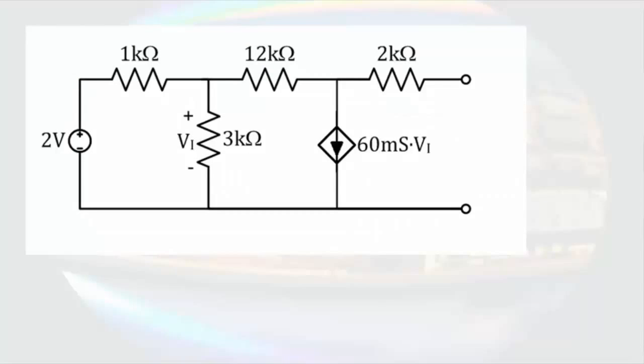If we remember way back to the beginning, the definition of resistance is a ratio of electric potential to current. So if we want to know a resistance, we can apply a test source and see what the response of the circuit is. That will generate a voltage to current ratio. For example, if I were to supply a known current to an element and measure the voltage that develops across the source, the ratio of the voltage to the known current would be the resistance of what we were testing.